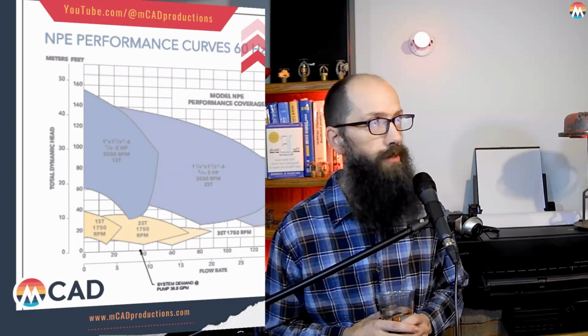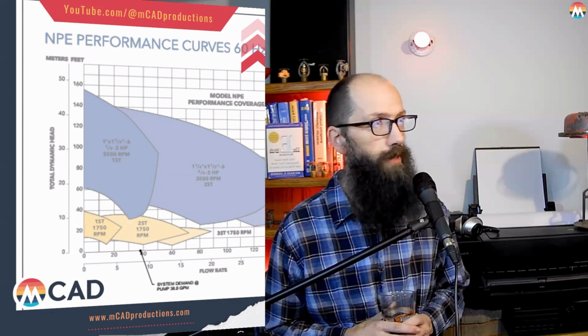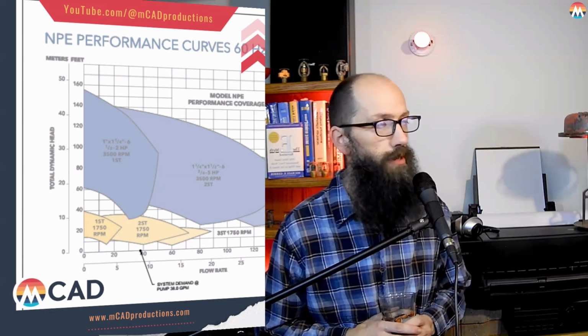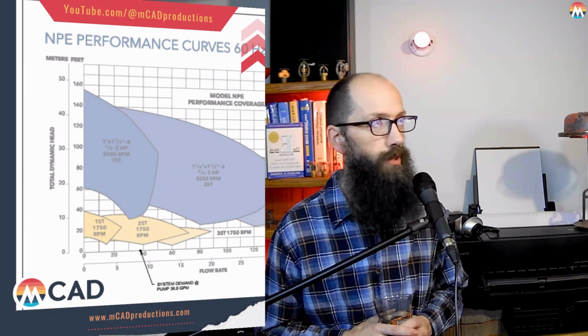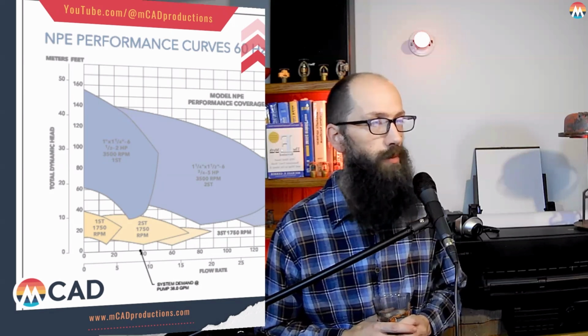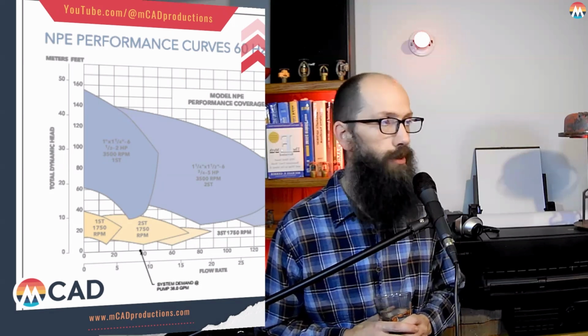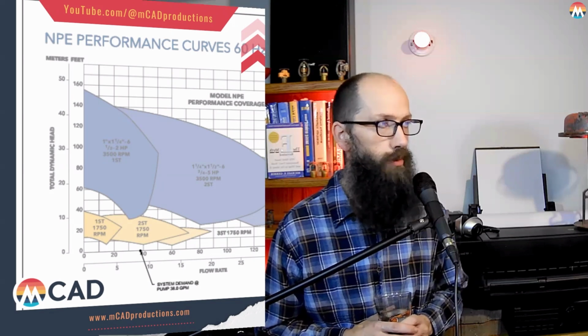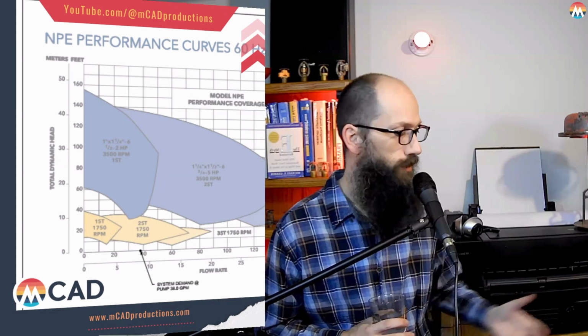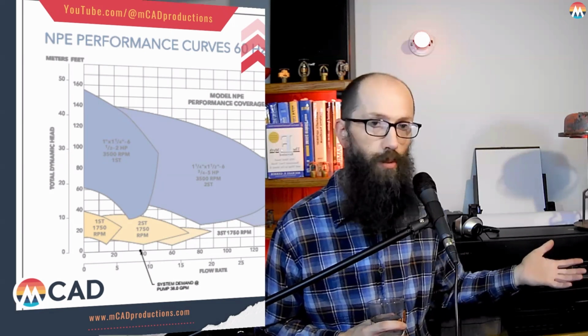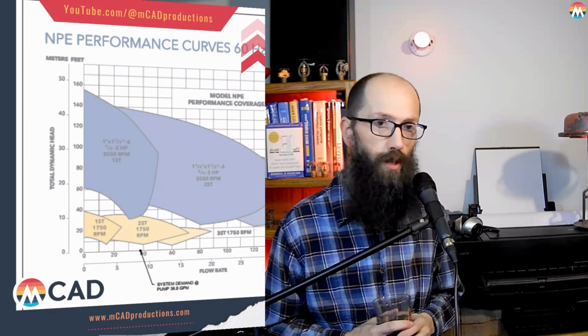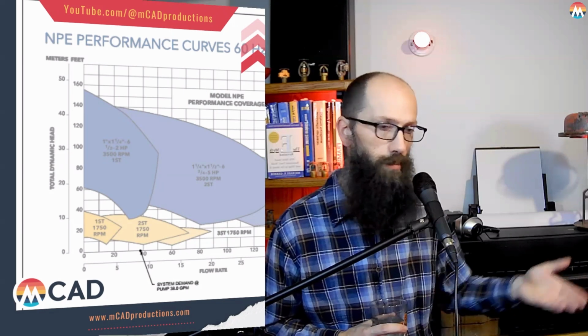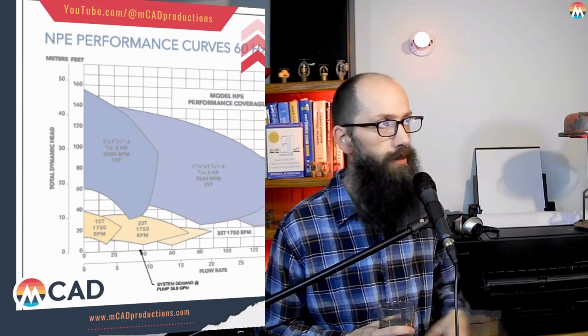One thing you'll notice too is that on the left we have, again, head pressure. So this pump is designed to work with sucking the water up 150 feet from below the ground. And in the situation where we had it, it was not doing that. It was sitting next to a poly tank, just like the pictures you guys saw of the home hydrant, but with a pump on the ground next to it, sucking it right out of there.